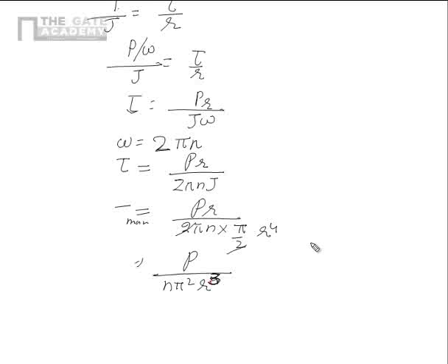So that's the formula for maximum shear stress in a bar which is transmitting power P at the rotational speed of n, and which has a radius of r.